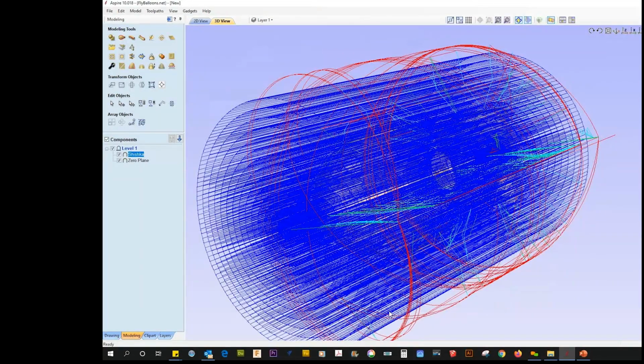So you shouldn't ever clip the corner of your stock. It will treat it as if that stock is round, which will start cutting the highest point first and working its way down into the low spot. It actually saves a little time, so you do not have to try to set up a rounding stock and setting up different tools. You're just using your regular roughing tool, and you can start carving the model right out. And like I said, you can get the maximum size model out of that piece of stock.